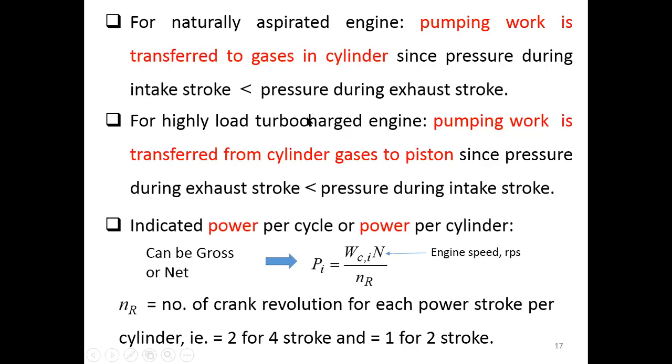So it has more power, right? So it can flow in easily. The engine doesn't need to give me the power, doesn't need to give me the money for me to get the ticket and go in, right? I can go in by myself because I have the turbocharger to help me, right? So the pumping work becomes positive. That means the engine gets the pumping work out because of the turbocharger.